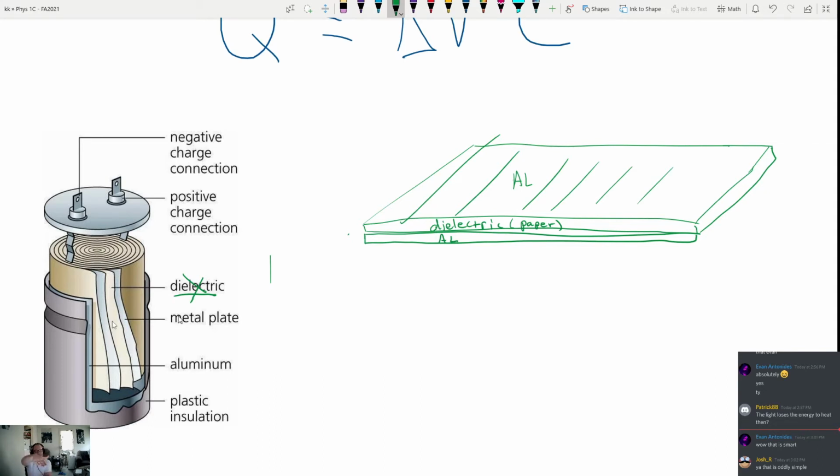So you've got a piece of metal, another piece of metal, and the oxidation layer created on the metal becomes the dielectric, because oxidized metal, like rust, doesn't conduct electricity very well. The point is that they make an incredibly thin dielectric between the two objects by allowing the metal to corrode at the surface, which means the thinness is incredibly small. And you can make the distance between the plates really, really short.